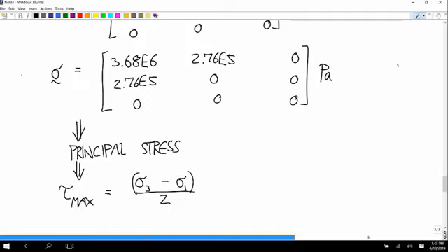Like a steel bar, you can bend it to a very noticeable angle and still be perfectly strong. If you found some kind of ceramic material that happened to have the same stiffness as steel, before you even saw it bend, it would break. And that's just a property of the microstructure of the material. That's something you'd have to look up that people would have done lab tests to figure out.